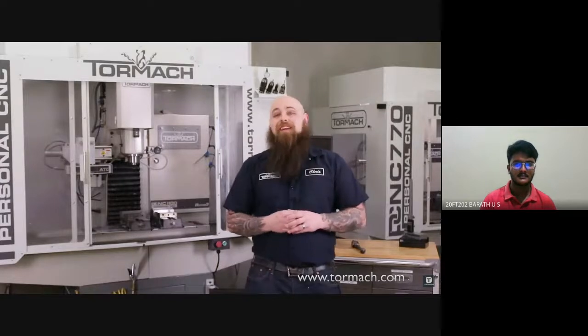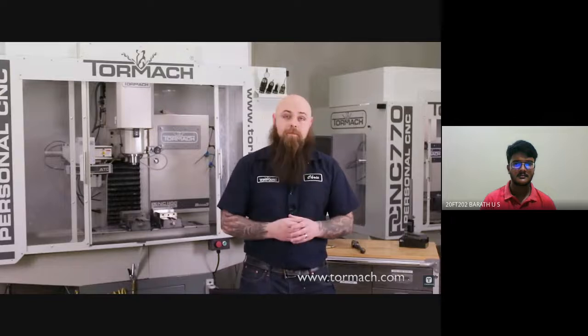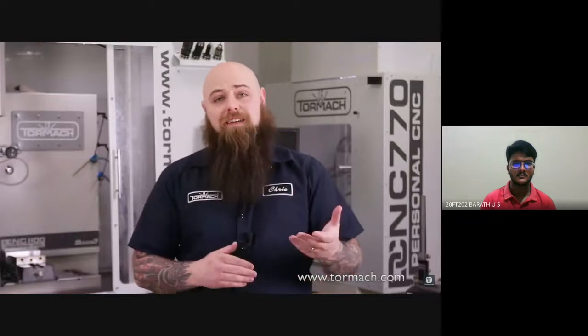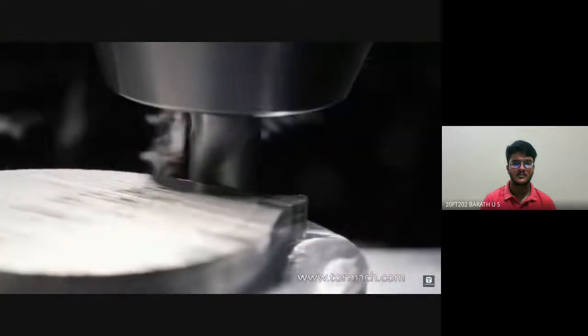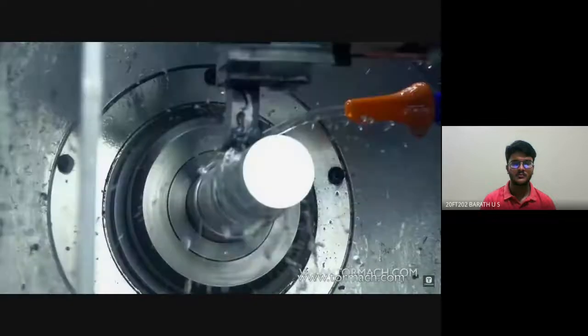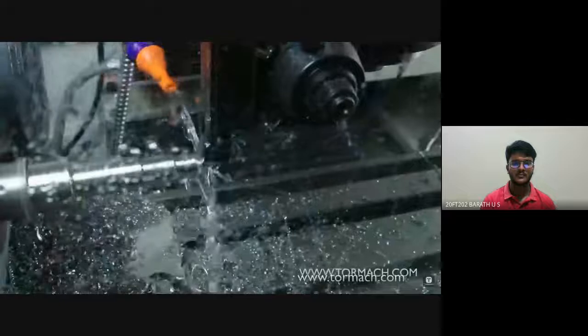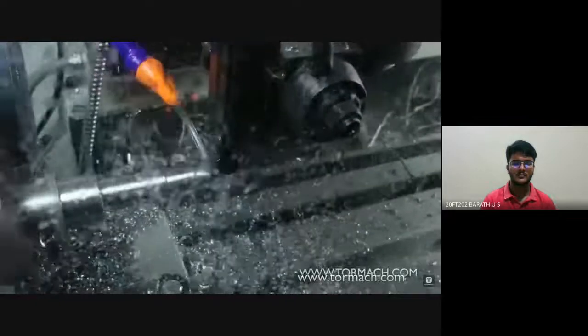On the other hand, steel is a much harder material. This generates more heat while cutting. While steel is less gummy than aluminum, the chips can still build up. With a hot cutter and mounting chips, it's best to keep things clear of your tool with an air blast technique. Now, stainless steel is harder yet, but still has some of the gummy features of aluminum, so flood coolant with high lubricity is ideal.